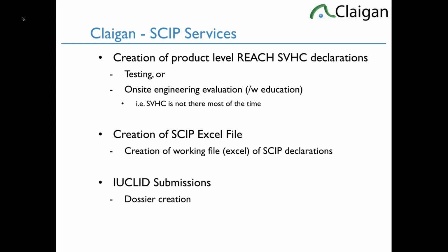You've got silicone. Do you control the siloxanes in it? Normally, no. Fair enough, we're going to declare D6. If you don't want to declare D6, then you're going to have to control them. Generally, that's not through the supplier, that's through testing, because the original monomer, the original solution before curing, is well over 0.1%, and it's completely dependent on how you cured the washer. If you're buying a washer from somebody, they may be able to control it, but they also have to know they have to control it, which is another problem.